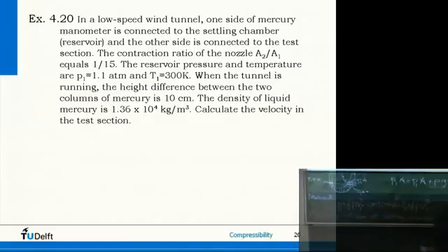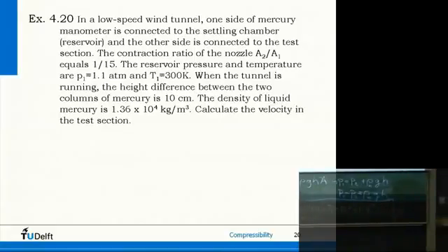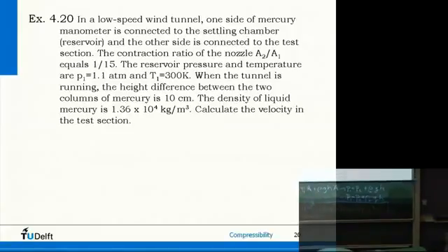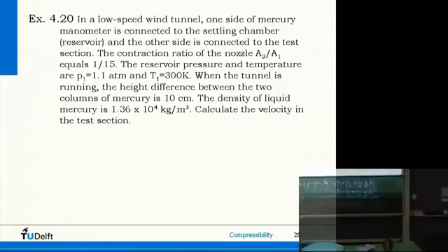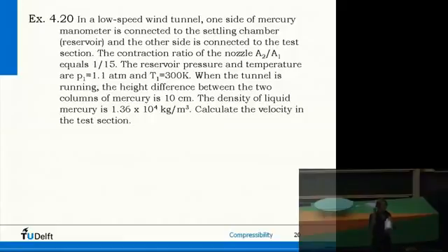P1, PT, P2 we know through the manometer. So then we still have one equation with two unknowns, V1 and V2. And it's a bit misleading maybe. Low-speed subsonic wind tunnels are much different from supersonic wind tunnels. Supersonic wind tunnels work with a huge reservoir under very high pressure, and then the flow is really injected through a very strongly converging, diverging nozzle.